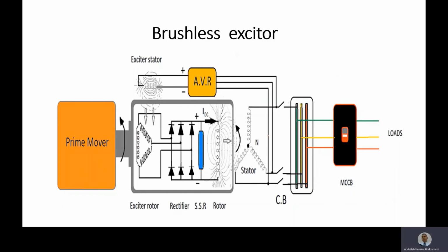So as a summary for the last section, when the load is increased, the voltage of the generator will be reduced, and also the speed will be reduced. Okay, the speed will be reduced because the magnetic field here will have more opposition with respect to the magnetic field coming from the rotor, so the prime mover speed will be reduced. And the voltage E will be reduced because you will have more current taken from the generator, so more voltage drop will be in the coils of the stator, so the output voltage will also be reduced, as we explained before.